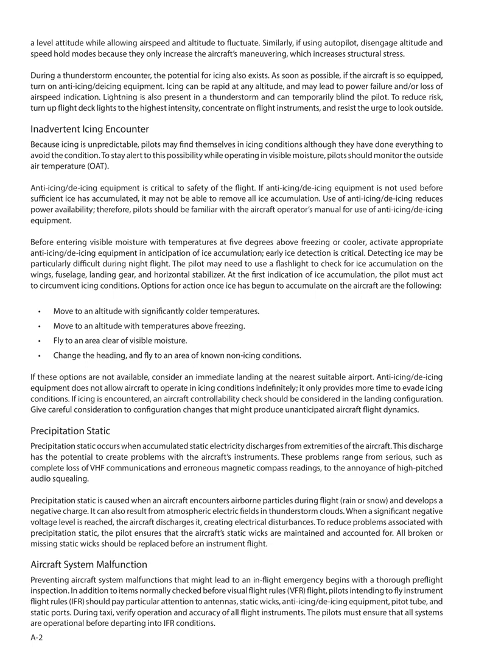When a significant negative voltage level is reached, the aircraft discharges it, creating electrical disturbances. To reduce problems associated with precipitation static, the pilot ensures that the aircraft's static wicks are maintained and accounted for. All broken or missing static wicks should be replaced before an instrument flight.